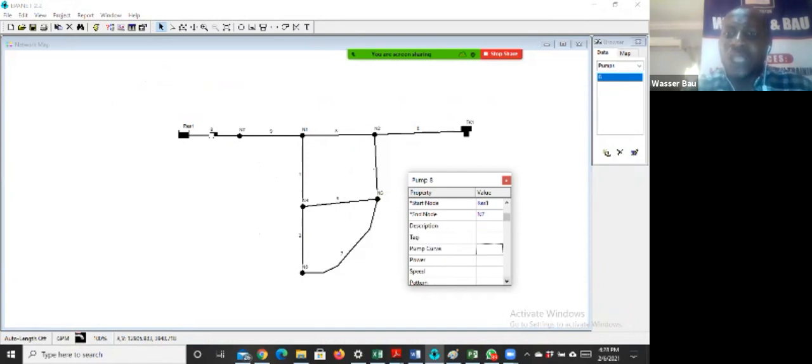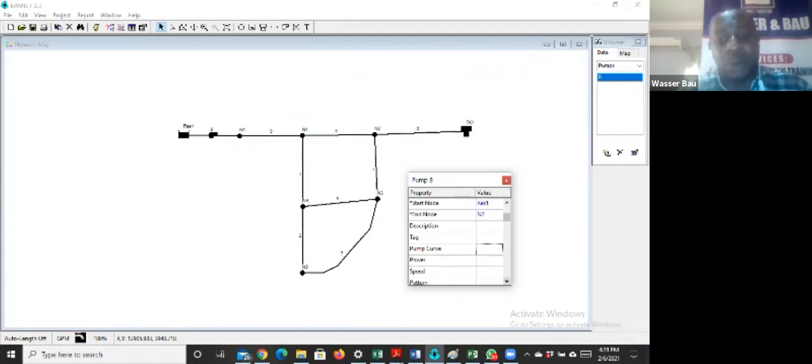So to size a pump or to buy a pump, there are 3 variables you can use. Either you use the head of the pump and the flow as parameters, or you use the power requirement, or you use the rotational speed. A combination of the head and the flow rate is known as the pump curve, which is the operational curve of the pump. The easiest way in the market to size a pump is to use the head and the flow.